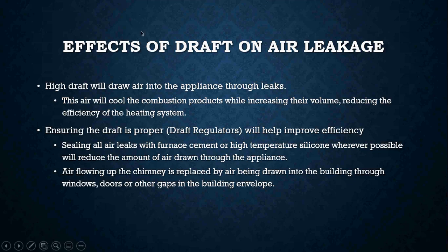Okay, effects of draft on your air leakage. If you have an appliance that has a high draft, it's going to draw air into that appliance through all the leaks that it has. This air will cool the combustion products while increasing their volume, which is going to reduce the efficiency of the heating system. So it's really good practice to make sure that the system is sealed.